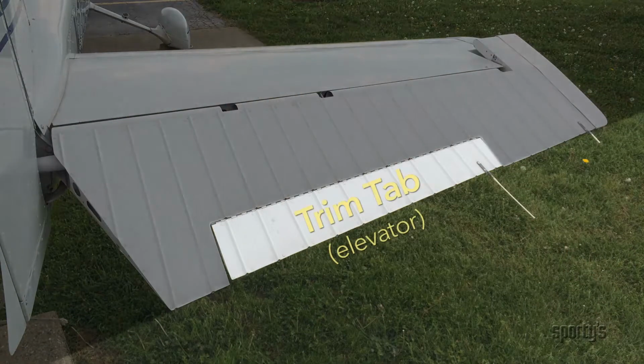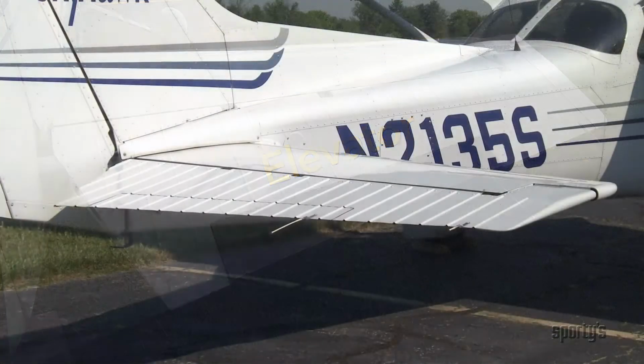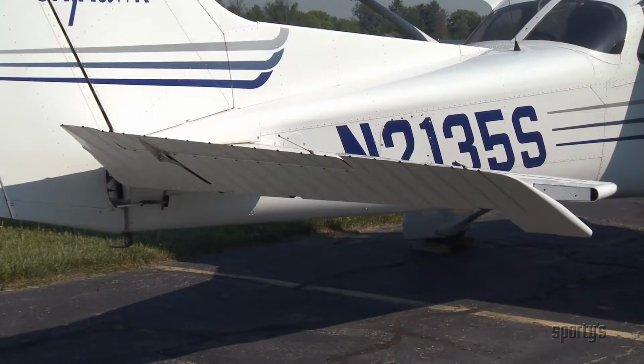A trim tab is used to relieve the pressure or force needed to hold a primary control surface out of the streamlined position. Trim tabs are attached to the trailing edge of the primary control surface. The elevator trim tab is moved opposite the position of the elevator to reduce the pressure the pilot must use to hold the elevator into the airflow.